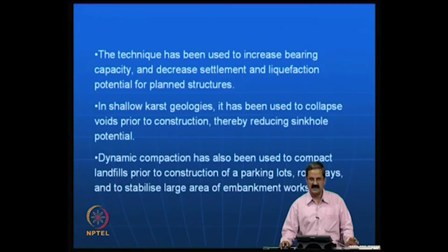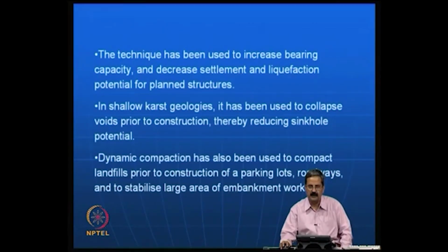It is very difficult to compact waste materials in a systematic way, but dynamic compaction has been quite useful. Why? Because it directly gives a lot of internal energy to the soil through this process, and the properties of the municipal solid waste are not directly related to the design.